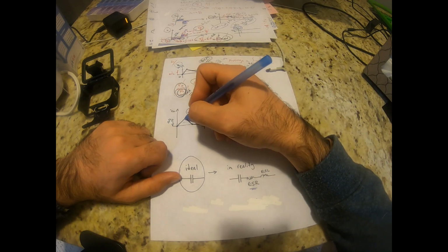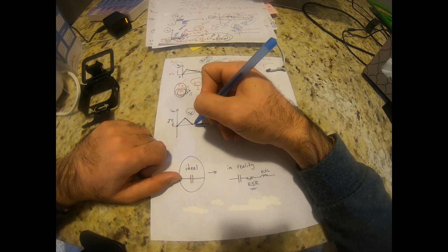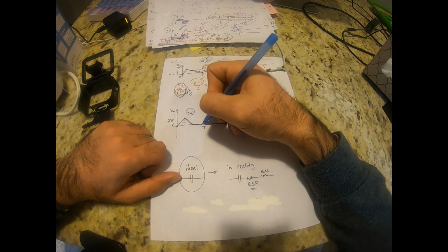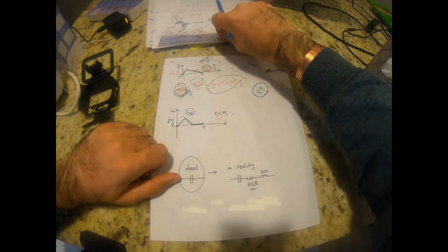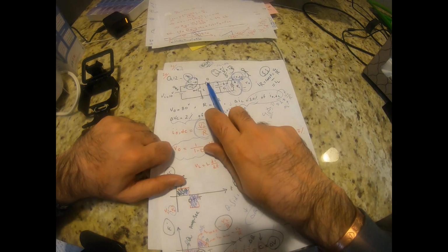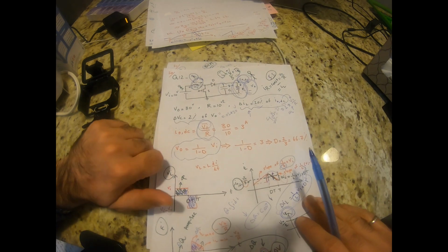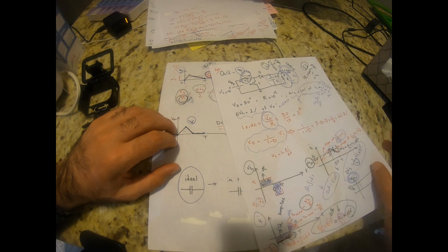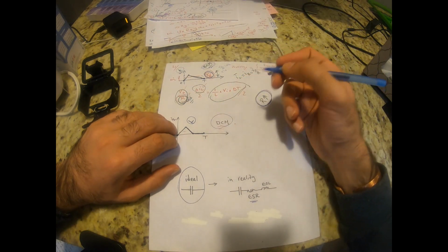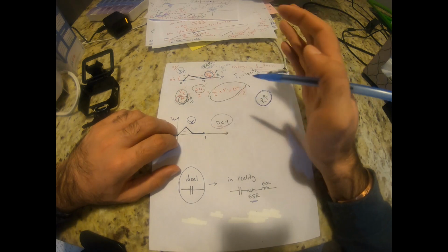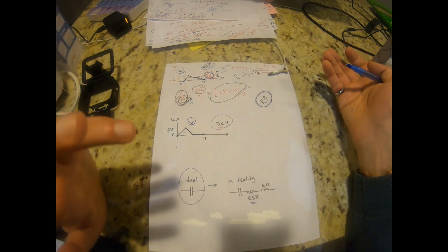It means that your inductor's current is going to discharge very fast before the end of the period, and the current becomes 0, and this diode would be basically disconnected. It's not going to be conducting anymore. This mode of operation is called DCM. You will see this in your future courses. I just wanted you to know what DCM is, what CCM is.